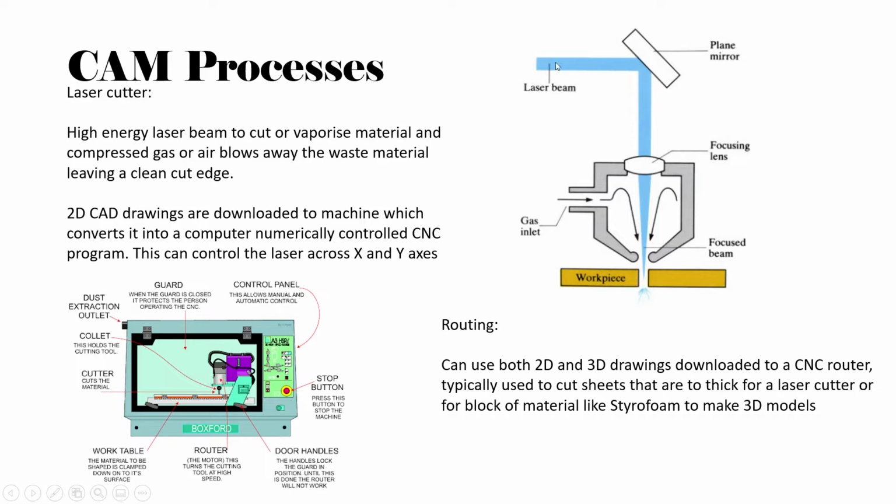So the laser beam hits mirrors. On our laser cutter, I think we have 3 mirrors. So the laser beam comes into the actual main compartment of the laser cutter, hits one mirror, that reflects onto another mirror, that then reflects onto the piece. Okay, and then for it to go in there, it's like a focal lens, almost like a glasses lens, that focuses it, and then it will cut it down.